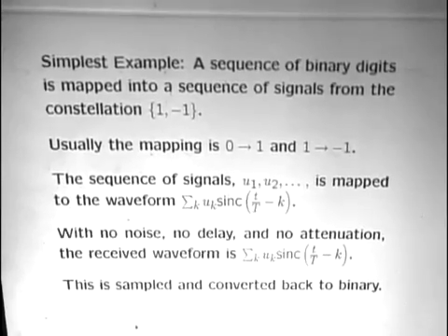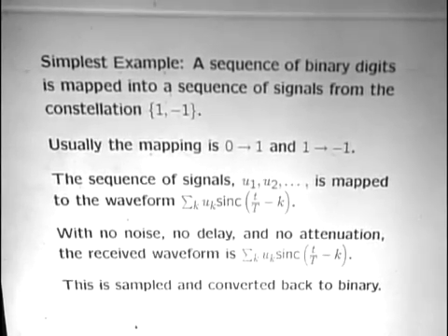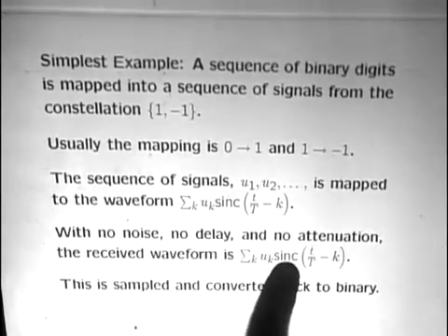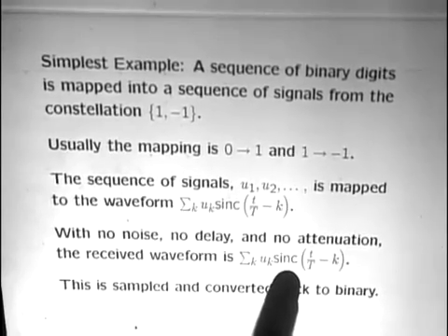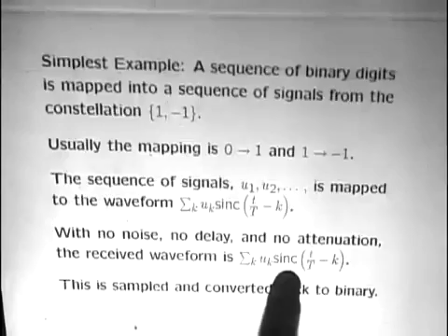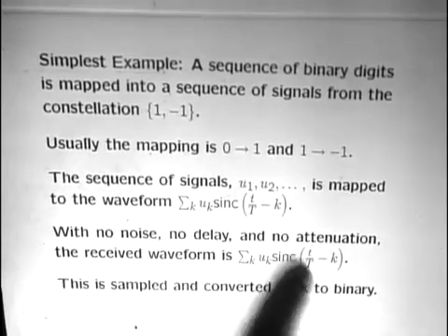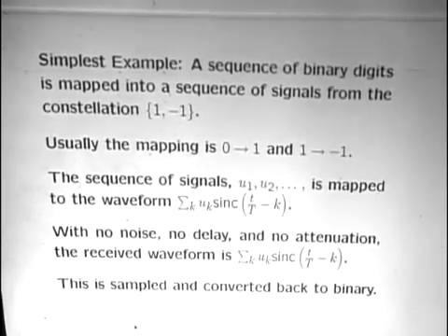Okay. So those issues we can deal with completely separately from these issues of what kind of waveforms we want to choose. What should we choose in place of this sinc function, which is impractical because it causes too much delay, and it's also hard to build the filters. Okay, so we'd like to deal with that question separately from the question of attenuation.